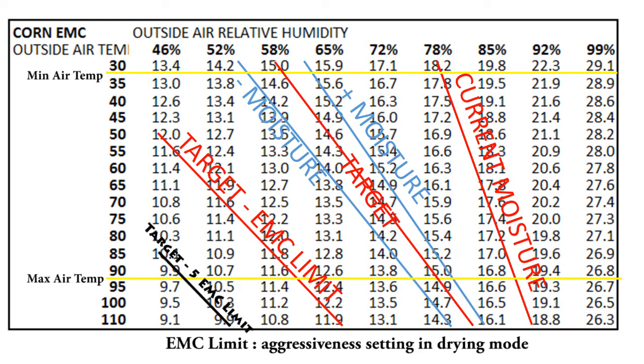The higher the moisture that you have in the bin, the wider the window you want, more fan runtime. The wider we can run because we can use some of that wetter air, because we're still drying below that 20% or 22 or whatever you have in the bin. So we can widen out that window. But as that moisture drops down, you start putting 17 in the bin. If we ran 5 points below your target or 7, then the potential to overdry, because you're actually running more below your target than above, is where you can have the potential shrinkage.